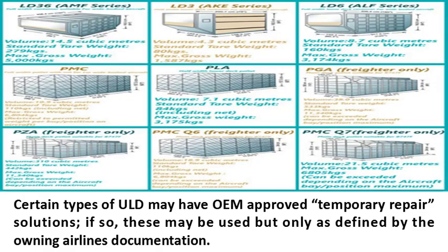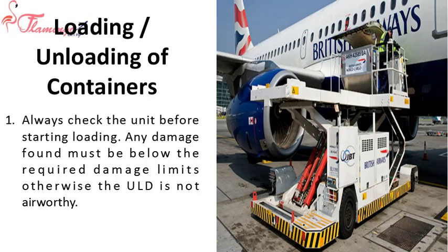Certain types of ULD may have OEM-approved temporary repair solutions. If so, these may be used but only as defined by the owning airline's documentation. Always check the unit before starting loading. Any damage found must be below the required damage limits, otherwise the ULD is not airworthy.